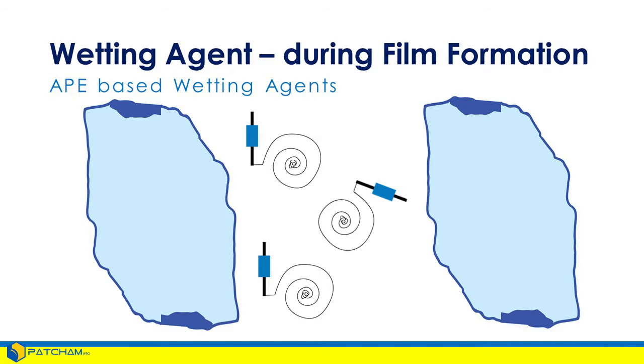As the ionic strength of the system increases, remember this is electrostatic stabilization around each of these pigment particles, when enough water leaves, the ionic strength goes high and the stabilization mechanism collapses. And it may be that these coiled up molecules are no longer large enough to keep those two pigment particles from making physical contact and flocculating.